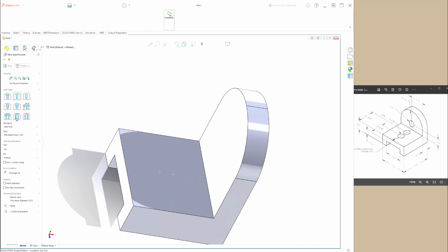Okay, so interesting here. If I do a drilled hole, it gives us those sizes. If I choose a flathead screw hole, we get different settings. And if we just choose all drill sizes here, I should be able to go bigger than 1 inch, but I'm not able to. So this is a slot, by the way. Okay. So since that's the case, we're going to have to draw it as circles and then extrude the circles instead of the drill hole sizes. It's unfortunate, but it is possible. I could do it as a tap drill, and it will work as a tapped hole.